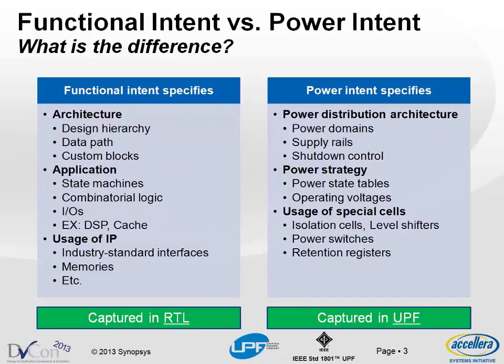You're used to designing your chips in VHDL, Verilog, some of you perhaps SystemVerilog. We won't ask for any SystemC folks here. But the point is, you know, I'm building a particular chip with a particular set of functionality. Now, when you start bringing in power management, how does this mesh in here? Is it really part of your state machine for your functional intent? Or is it really part of your power intent? Here are the things that belong in your functional intent, and by the way, here are the things that we would introduce you to club into your power intent.